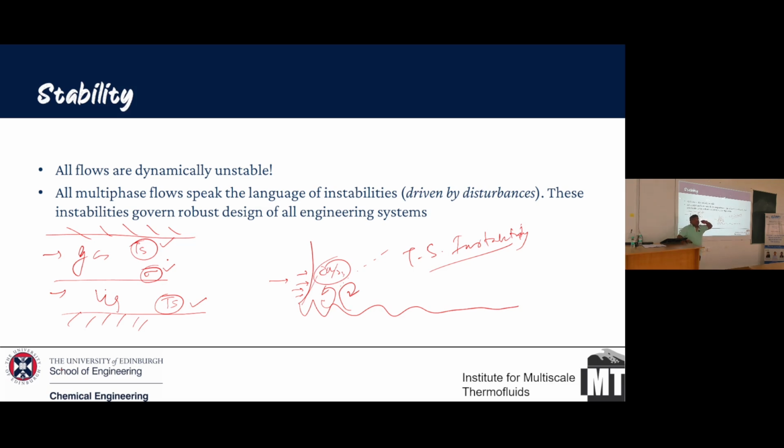If you look at a completely stratified system at low gas and liquid flow rates, you might find the interface has slight disturbances but is ultimately nearly straight. It just means the instabilities are not very strong. But as you increase your gas flow rate or your liquid flow rate, you'll see waves developing on the interface, not because of the bulk mode in the gas phase or the liquid phase, but because of the interfacial mode, the surface tension, which is playing a role here.